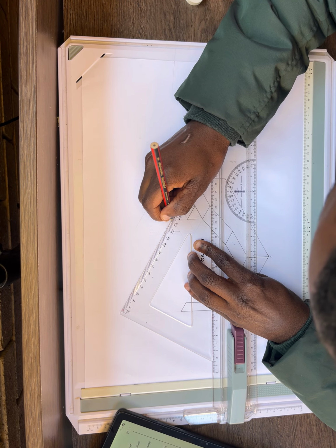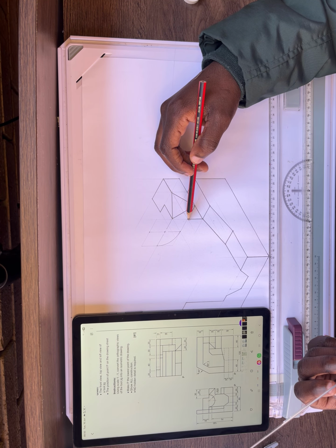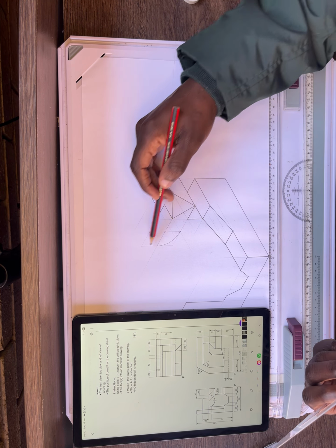Then now I have to get the arc in this position, but you know, to get the arc in this position, you first have to do what? You have to do the what? The construction line. You're going to take a line all the way from here to the other side. Construction line, just like this. From here, it's passing here all the way this side. Then second one, you will take it from here all the way to here. Then this point here, it's where you are going to put the what? The point of your compass and start making an arc. So let us do it.